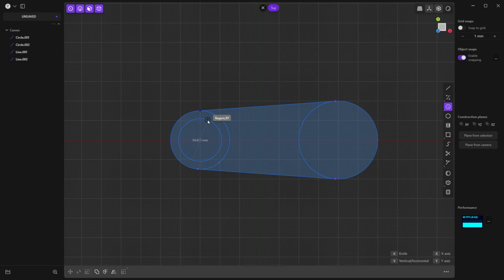I'm going to go back to the center point here, begin dragging this out, and I want to make a quick note here as well. As we're moving this out and I'm snapping to a vertical position, wherever we click is going to be the start and end point of a circle. Now, this may not seem like a big deal, but in some instances, you want to be very careful where you put that point because you may need to trim or snap to it later on.